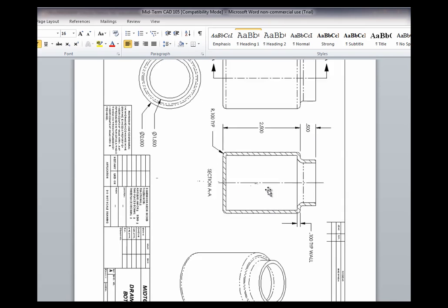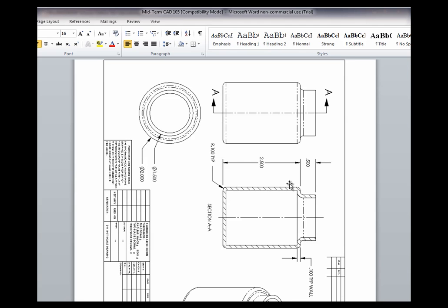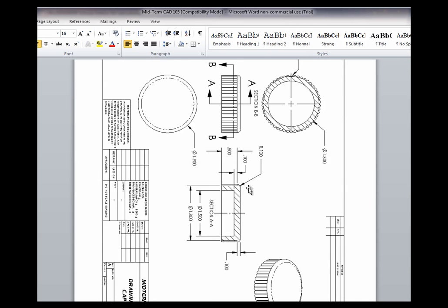Here you can see the bottle design. The bottle is very simple. It's basically just 2 cylinders, one on top of the other, and then the dimensional parameters given. There's some rounds that are put in, and then it's shelled at the end. The cap is a little more complex, but yet pretty simple. The very top of the cap is a 1.9 inch diameter, and then it's only a thickness of 100 thousandths. Then we have some ribs and a cutout that we're going to make.